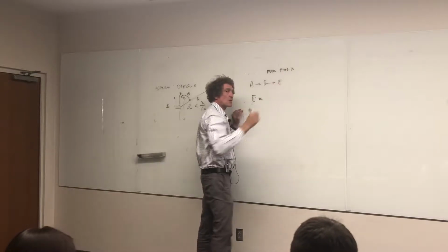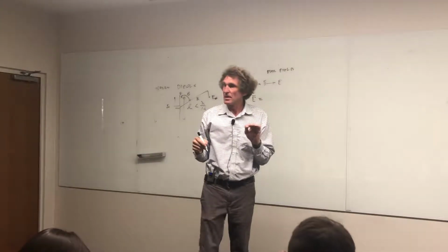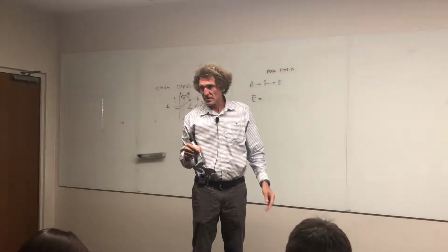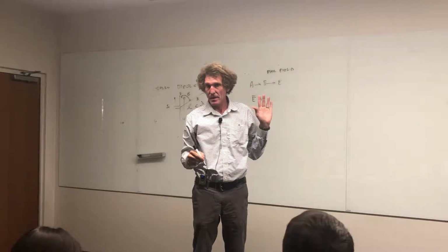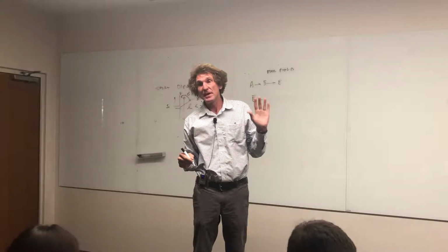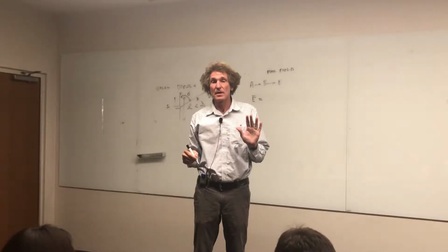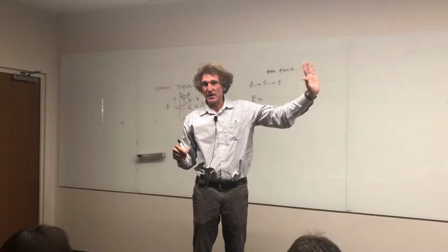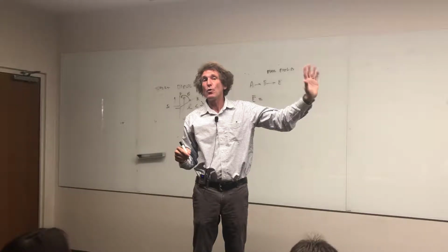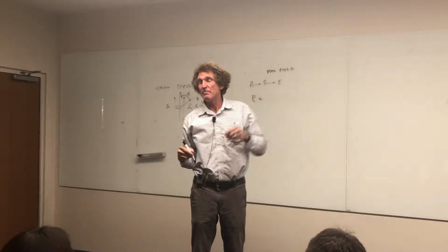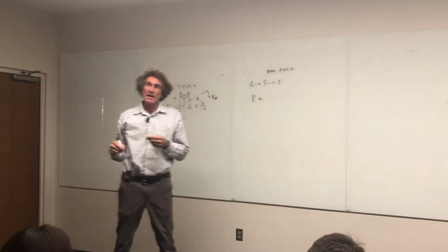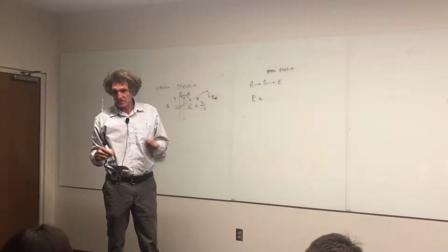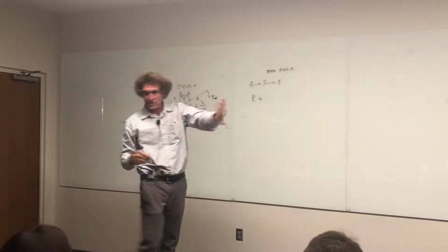And by the way, what's the far field? I mean, in your own words, what is it? Not the equation. What's the difference between being in the near field or far field? Anyone? All the energy is propagating, right? You're talking about no measurable or appreciable amount of magnetostatic or electrostatic energy. Do you follow me? These are fields that are launched for good.